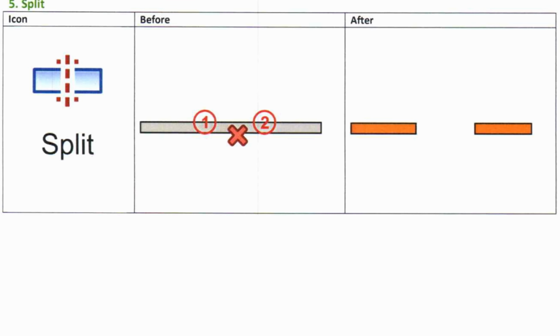Split tool, segmenting linear elements. Purpose: divides walls, lines, or similar elements into separate segments. Useful for layout adjustments, phasing, or isolating geometry for editing. Workflow: 1. Activate the Split tool from the Modify tab. 2. Click two split points, for example point 1 and point 2. 3. Optionally, tick Delete Inner Segment in the Options bar to auto-remove the middle portion. 4. Result: 2 clean segments remain, butted end-to-end.